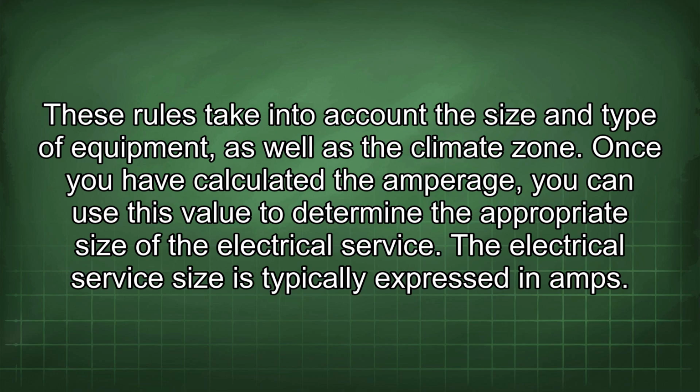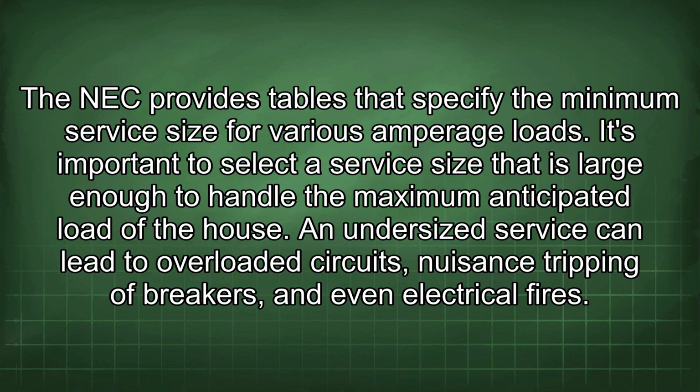Once you have calculated the amperage, you can use this value to determine the appropriate size of the electrical service. The electrical service size is typically expressed in amps. The NEC provides tables that specify the minimum service size for various amperage loads. It's important to select a service size that is large enough to handle the maximum anticipated load of the house. An undersized service can lead to overloaded circuits, nuisance tripping of breakers, and even electrical fires.